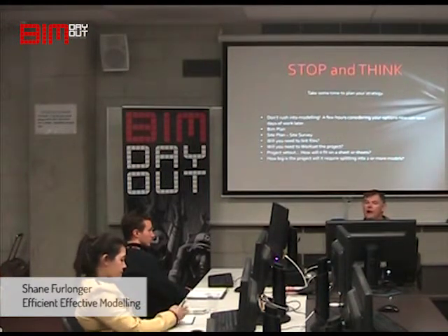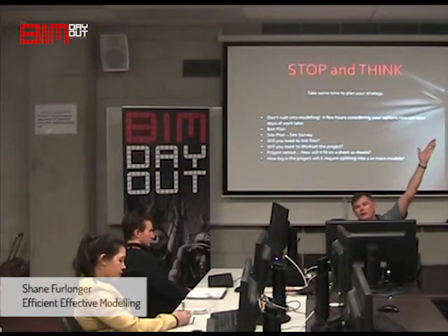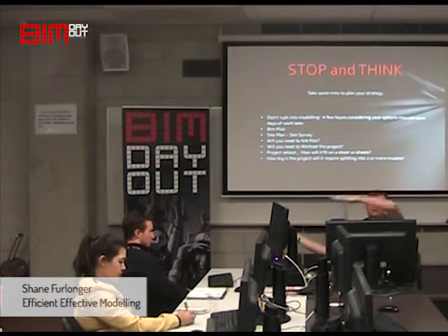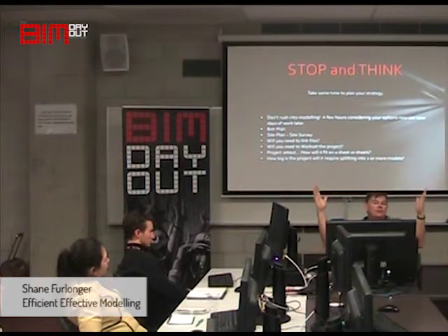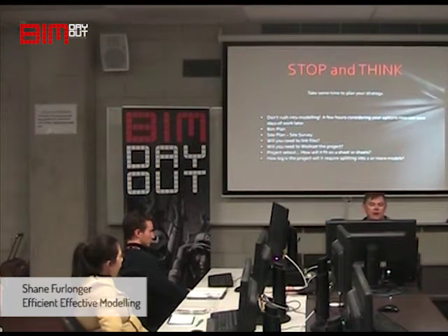So you have to look at how it's going to fit on those 2 sheets or 4 sheets or whatever it's going to be. That's what I'm saying about fitting on a sheet. Real north might be here, but you might have your project north over here just because that fits on your sheets. You don't want to have 7 sheets when you can have 4. So the less the better.